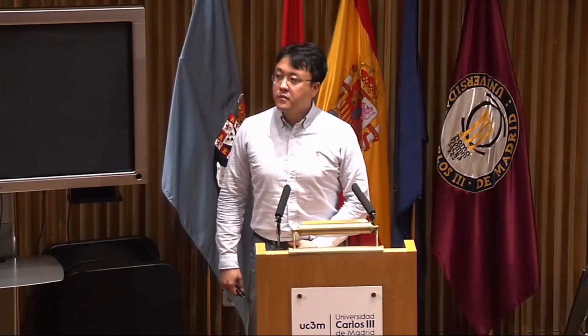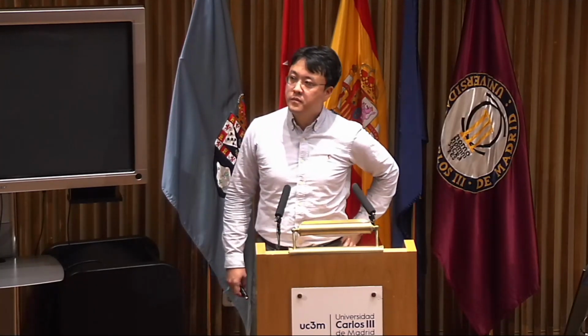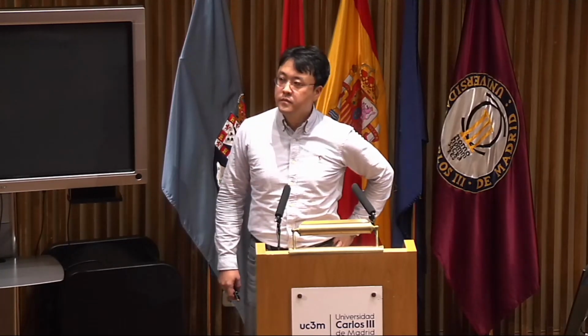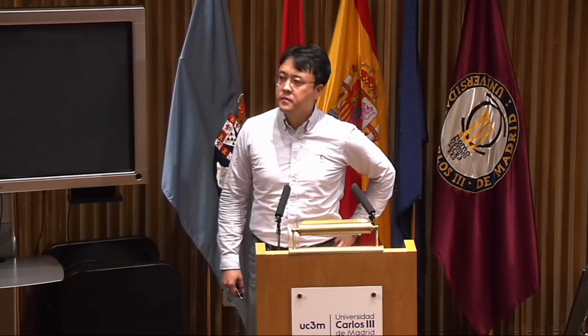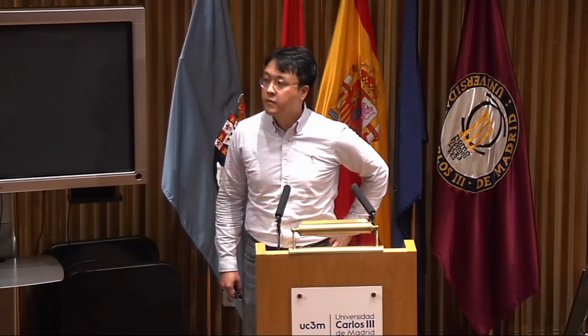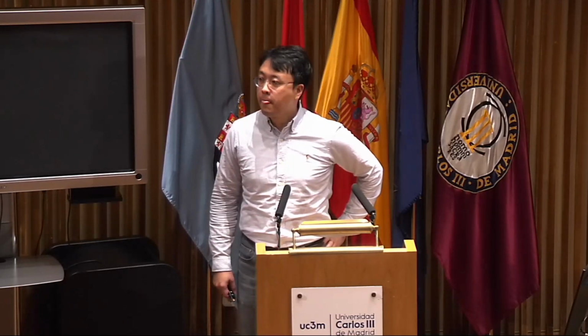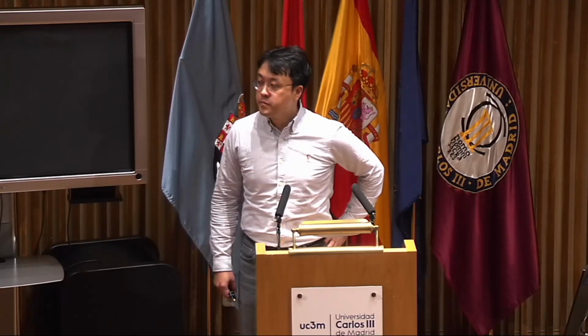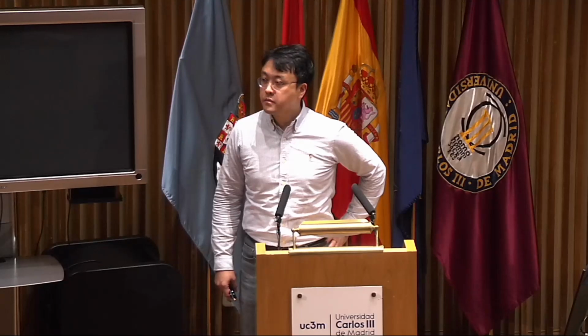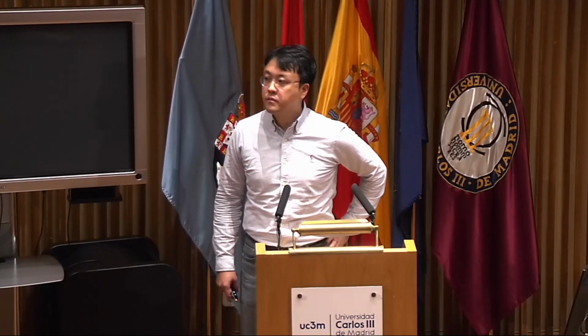Thank you for your talk. It was very interesting. I have a question about the current balance in the thruster. Since you are emitting ion particles, you have to collect electron current somewhere to compensate for this ion emission. Are you collecting it in the screen grid or in the injector?